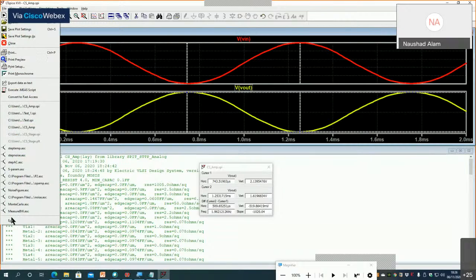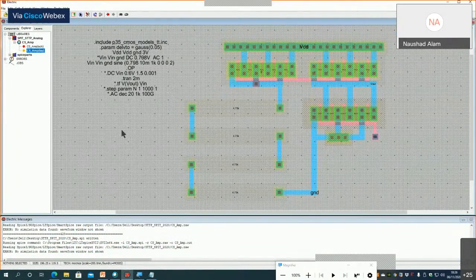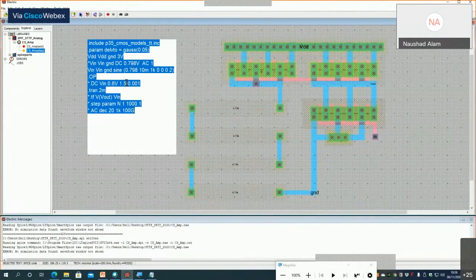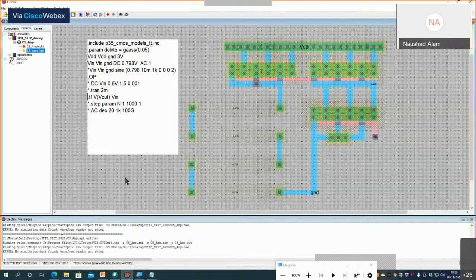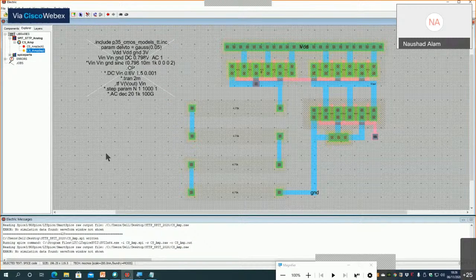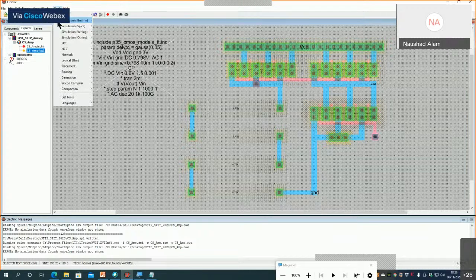Now again, I skip this LTspice instance, and this has corrected automatically. You can see some magic has happened. So now we go again, and now we do transfer function analysis. So I go here, I left click, and I do a transfer function analysis. Now I go and invoke the simulation again, write SPICE deck.